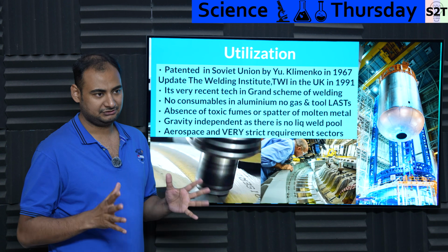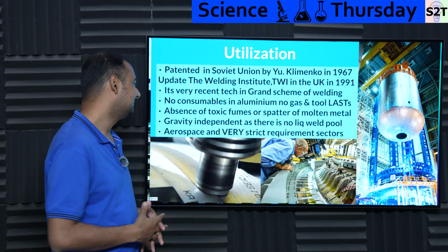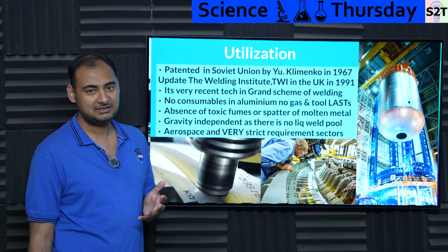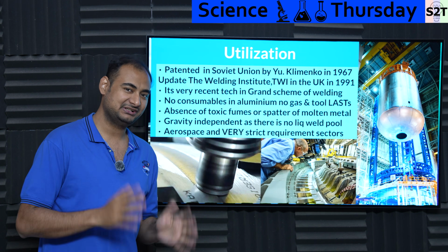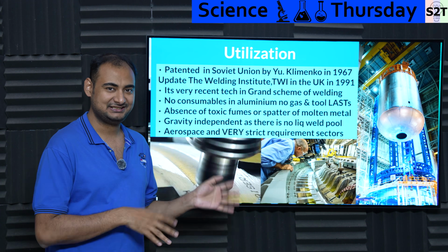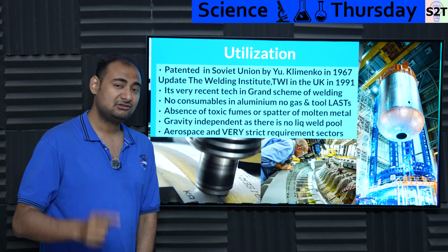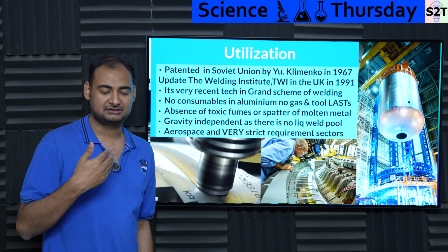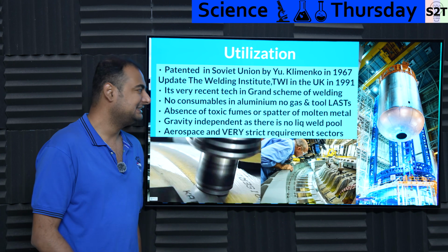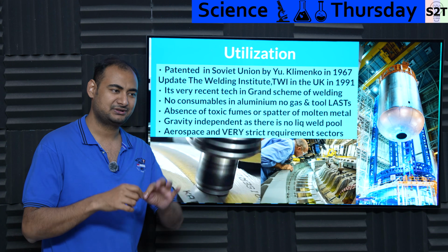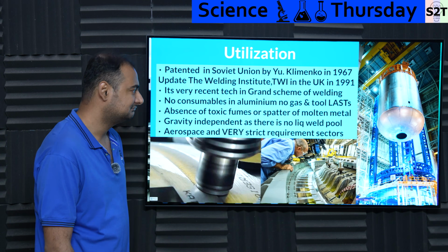So there are not that many people who are experts with this, because it is so new. And no consumable, that's a very big deal for industry. It's like, you're telling me that I do not have to deal with argon, nitrogen, or this or that? Shut up, take my money. And the tool, what about the tool? That also lasts a very long time. Of course, it's not going to last as long as a laser, because the laser is non-contact, but it does last long enough, meaning they say you can go up to 1 kilometer of weld before you have to do anything to it. So that's decent.